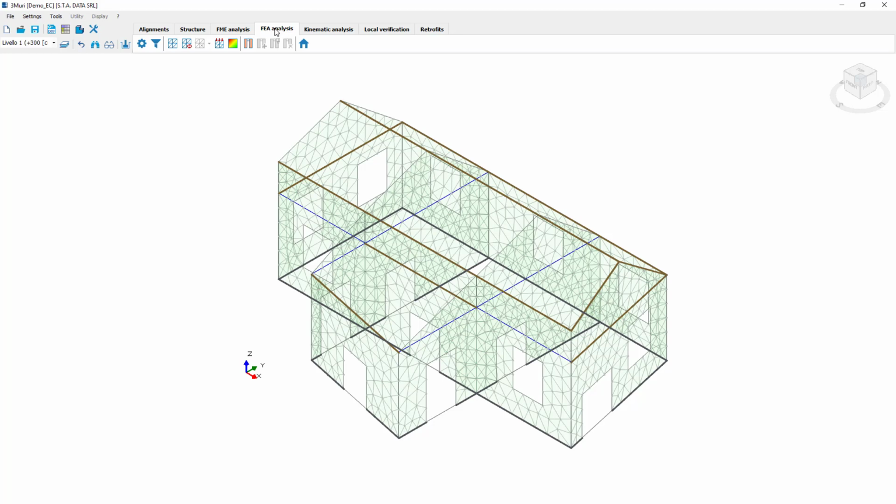So in many cases, we're going to be presented with the choice of which method to choose to analyze our structure. Of course, the two different approaches have different advantages and disadvantages. The frame by macro element is, of course, our classical approach, and the FEM analysis is going to present several advantages, but usually because it's going to take a bit more calculation time, it's going to represent a compromise. So how to choose between the equivalent frame approach and the FEM approach?